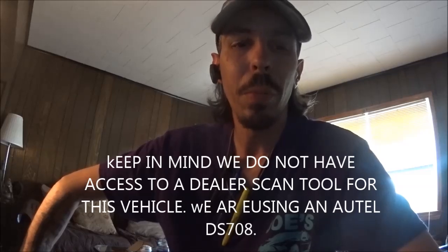Okay, so the next step was we did an auto scan on the vehicle, which is in manufacturer, and the scan tool will allow you to go into any active modules and communicate with them and check for codes through all of them. So that's what we did, and we came up with a number of codes for all types of things, which I'm going to show you in the video here in a minute. We had communication issues with the PCM. The PCM was not active in manufacturer specific. Okay, so let me show you here the codes.